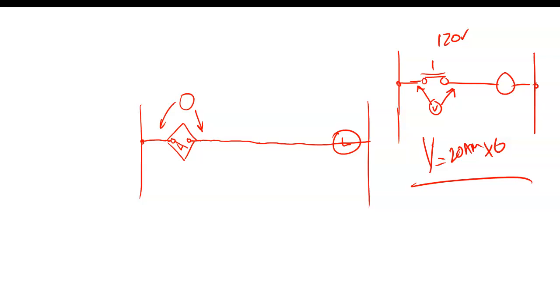But when we measure across this, if it's got to power through the load, and when this switch right here closes, it's got to power through the load. So these guys are going to drop a voltage, right? I think ours drops between 4 and 6 volts because it's got to have power. Does that make sense? But still, if I've got 120 volts over here, that still leaves me, what, 116 volts, well, that would be 114 volts, which is still plenty enough to power a 120 volt load, right? You understand that? So these guys are going to drop a voltage.